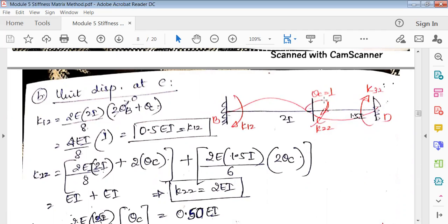Okay, so when you apply a moment like this, that is, here there is a rotation, apply a rotation here. So when you apply a moment here, CD bends. Okay, CD bends downward. Again the same moment, if it is acting in BC span, it will push the beam upward. All right, so now B, C, and D. So after you draw this deflected shape of the beam, then mark K.